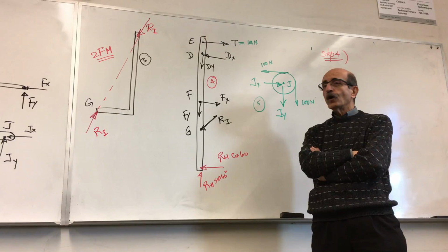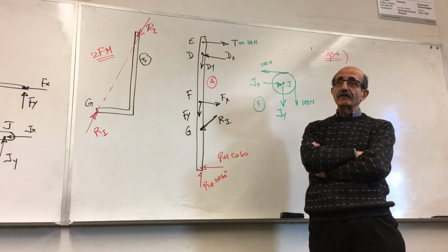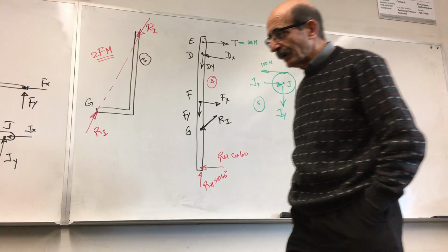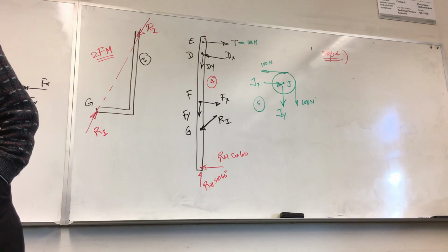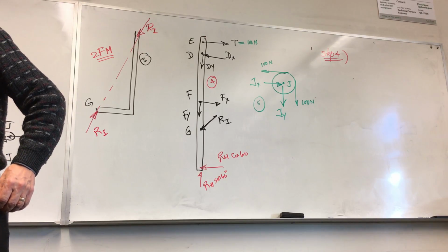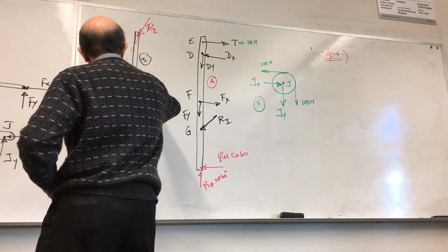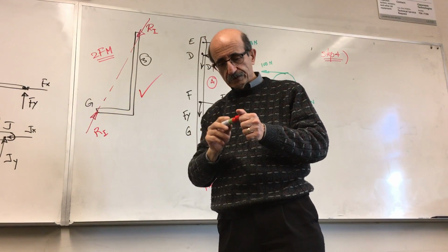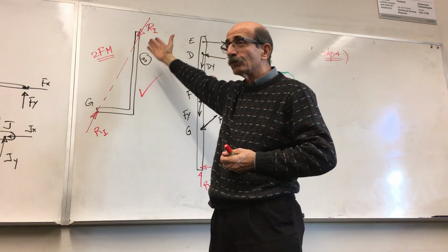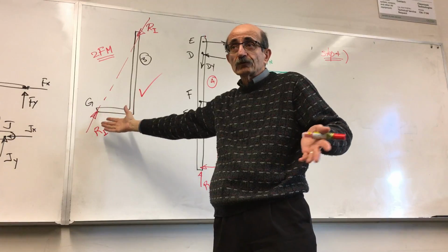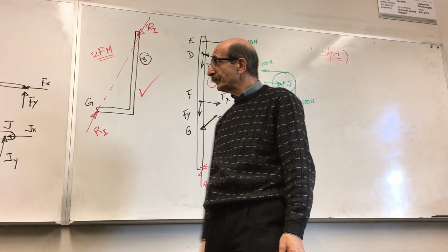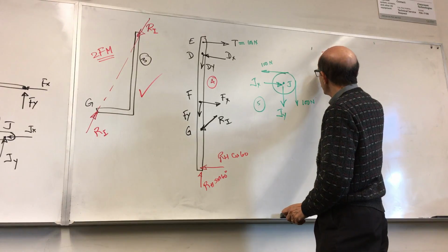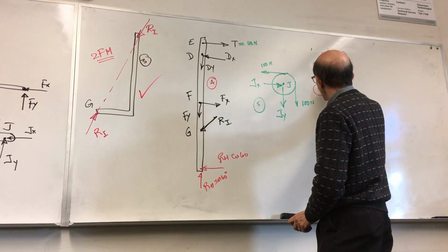In fact, you already applied the equations of equilibrium to figure out that these two forces are equal in magnitude and opposite in direction. So because of that, remember that diagram for the two-force member is useless. So that I have already used. Any free body diagram you've already exhausted all your options on, put a check mark next to it, right? Because here you have only what? Equation, sum of forces along x and y equal to 0, which gives you those two being equal. So what free body diagram is next then? 5. So I would put here 3 already used. I'm going to start with 5.